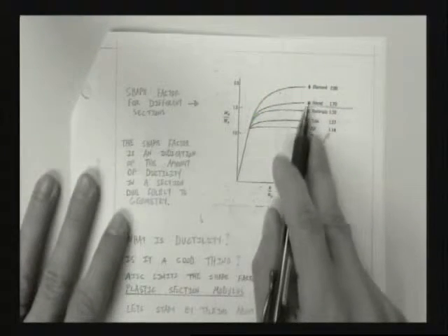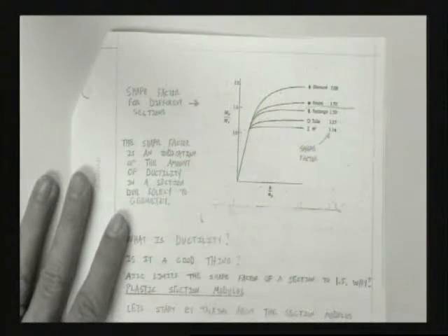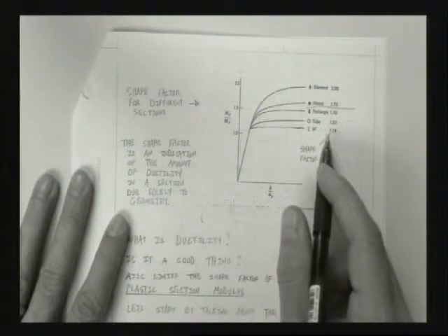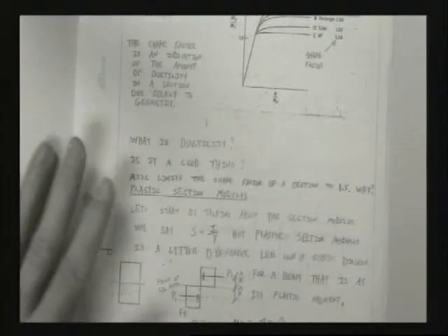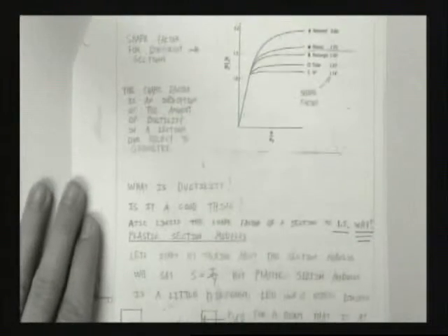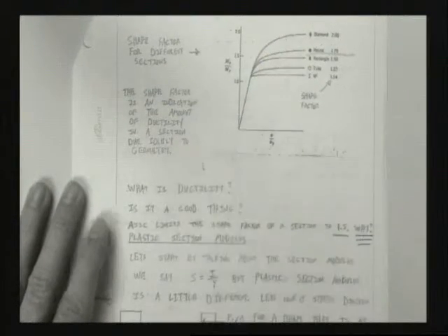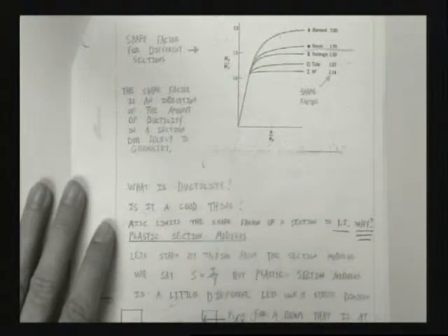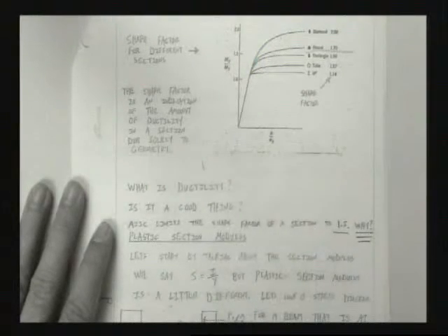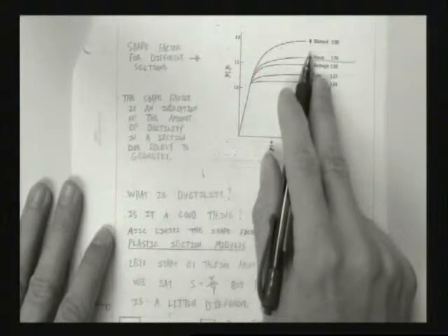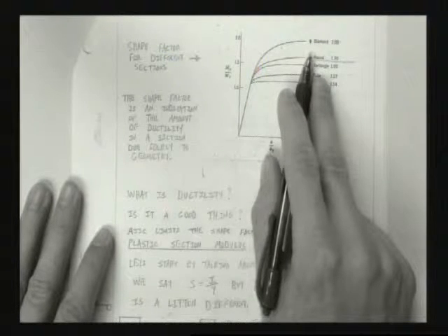The cross sections actually will give you different ductility. Well, that's kind of cool. So if that's the case, then in ductility, I say, what is ductility? Hey, it's the amount of material underneath the stress-strain curve. ASCE limits the shape factor of a section to 1.5 currently. And then I ask the question, why? Why would we limit our shape factor? Why would we limit our ductility of our cross-section? Ductility is good. Why would we limit it? Why don't we have diamond-shaped beams? They are.